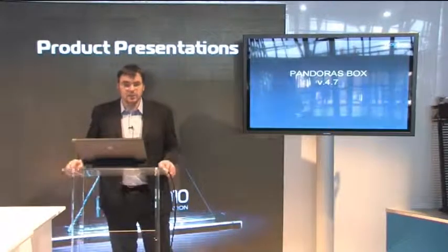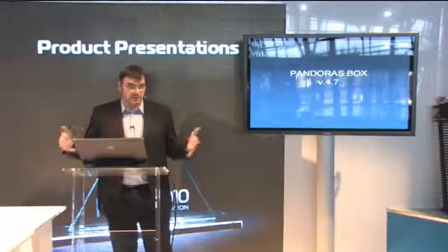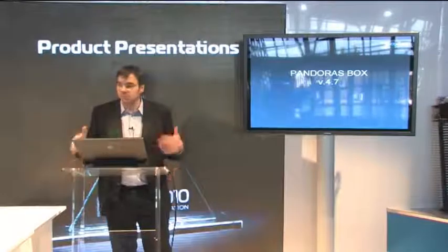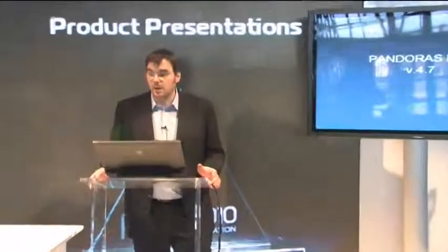DVI or VGA, but this signal is unsynchronized. It runs by itself. It has its own time and own beat. It's independent from the video rate or from a video input card. This leads to an undesired effect that happens here and there. A little dropout, a little stutter, a little jitter, and that for corporate shows or live events can make a CEO very unhappy if they're very picky about image quality.